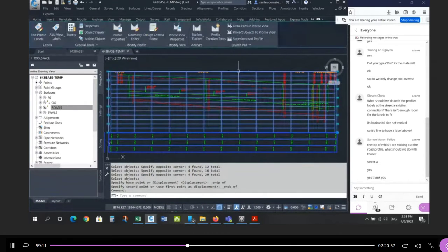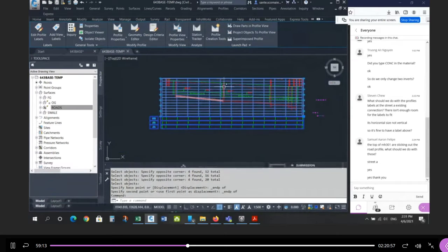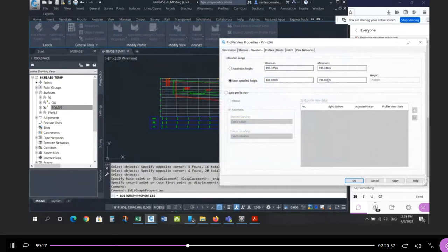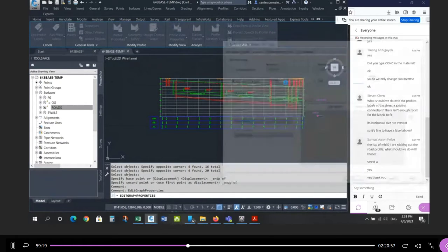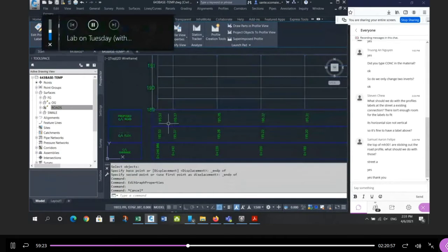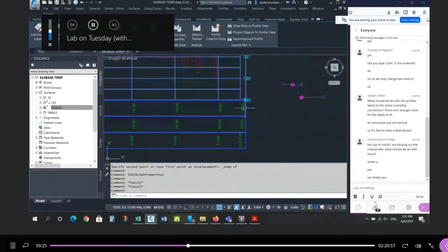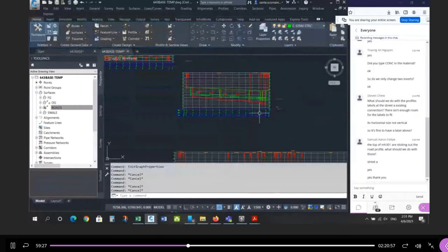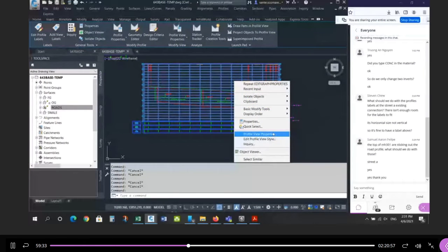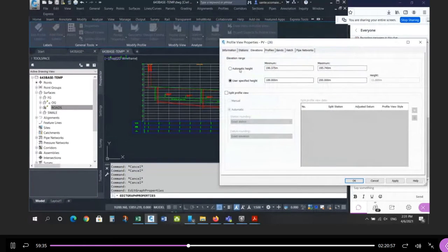You can raise the grid, you can raise the top, but if you lower the bottom, you might have to make that adjustment. If I go to Profile Properties, I can raise the top. I can add to this 200. It doesn't change that. This is fixed. The insertion point of the grid is fixed. So if you add to the bottom, it pushes everything up. You can add to the top, but you can't lower the bottom or change the bottom, right?